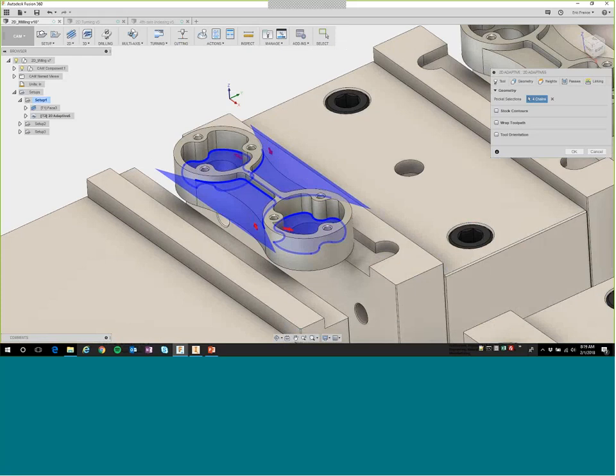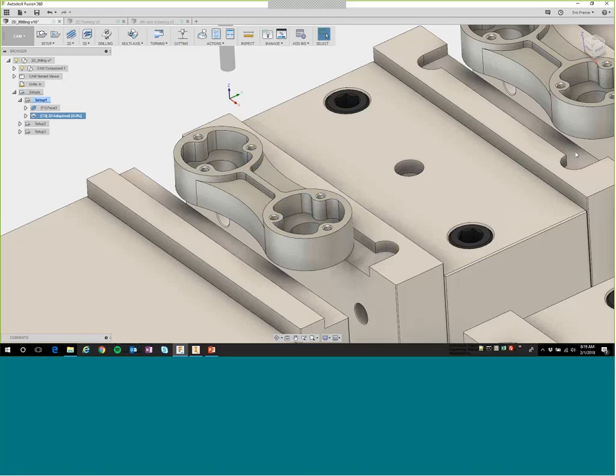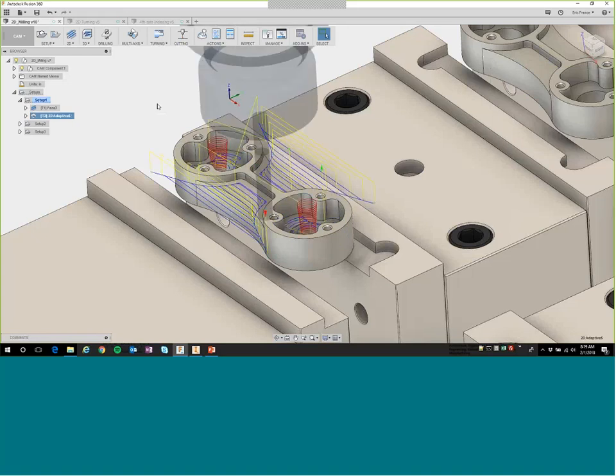So I went in and identified the edges that I want to set up, including a couple open contours for those pockets on the top in between the 2 ends. So we're going to have it clear that out and see what that looks like, just in the calculation that it makes. We can see that it's going to do a tapered heel down into the pocket.